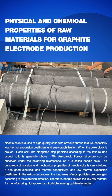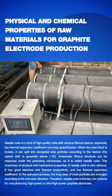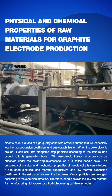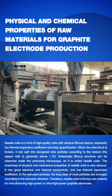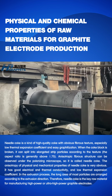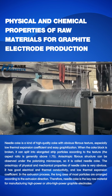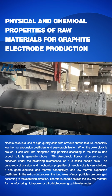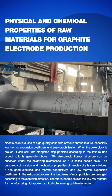The anisotropy of physical and mechanical properties of needle coke is very obvious. It has good electrical and thermal conductivity, and a low thermal expansion coefficient. In the extrusion process, the long axes of most particles are arranged along the extrusion direction. Therefore, needle coke is the key raw material for manufacturing high-power or ultra-high-power graphite electrodes.